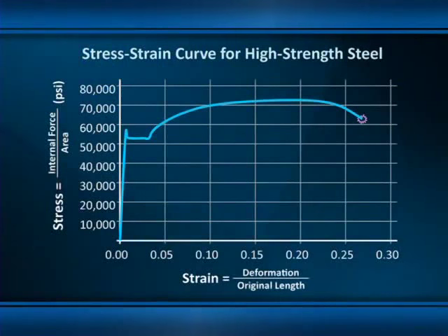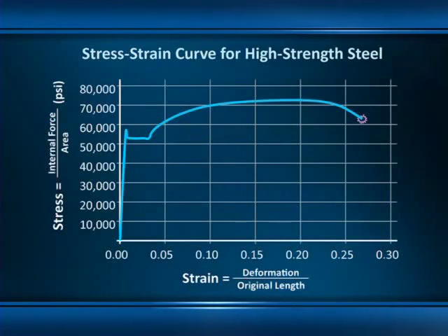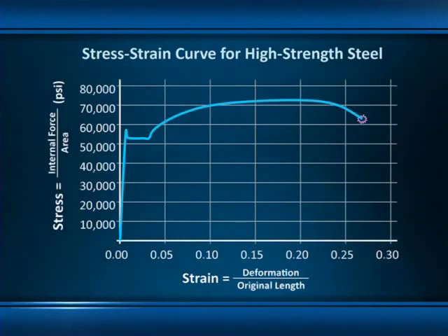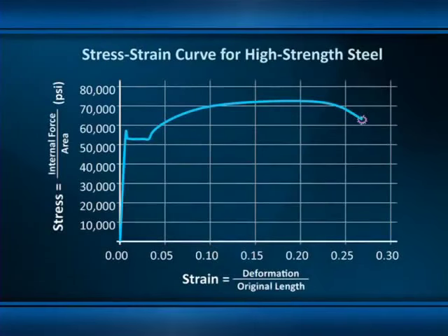And here we see a typical example of a stress-strain curve for structural steel straight out of the laboratory. The stress-strain curve is an extraordinarily powerful tool because it characterizes not just the specimen that we tested, but the material that that specimen was made of. In other words, if I test 10 different specimens of different shapes and sizes that are all made of the same type of steel, then the stress-strain curves for all 10 of those tests will look exactly the same,